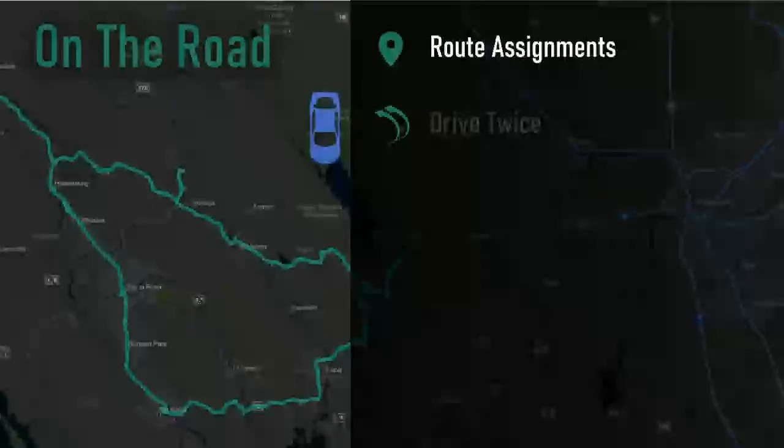The route assignments are a very important aspect of what we do. We drive each area or each roadway centerline mile twice, per the recommendation for CARS. So that's part of what ends up being so many more miles. And then you have deadhead miles that you do just getting to a start and end point lots of times.